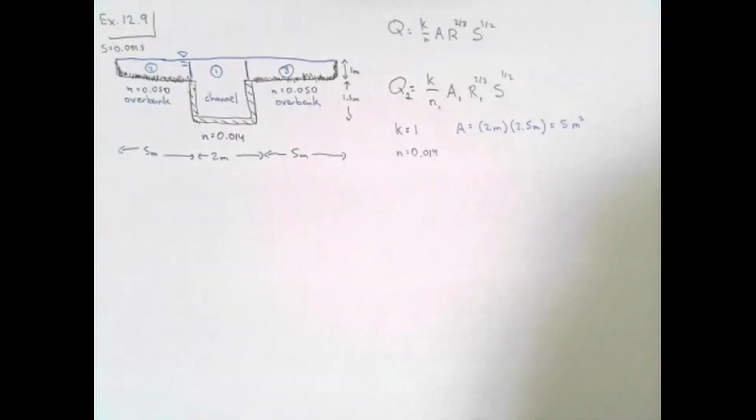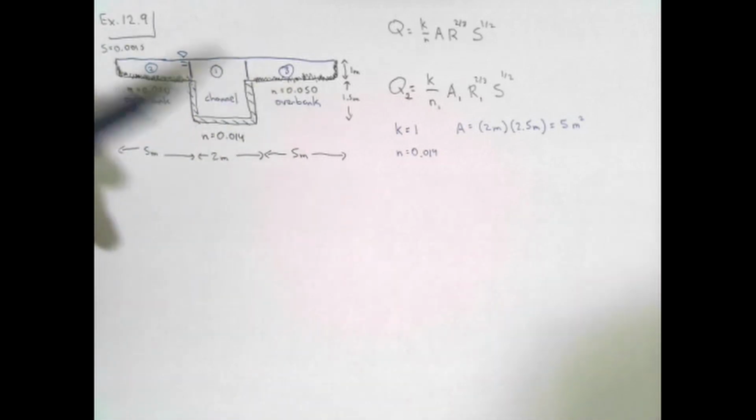Now, there isn't a textbook solution for choosing the method you want to use. You can use this, and you'll find that for some channels, splitting your channel into these vertical segments doesn't give you realistic answers. So I do want you to be aware of that, especially for the take-home exam. Be aware that this methodology won't always work. And if that doesn't work, you're going to have to find different ways of reconciling these different roughness coefficients. But we're going to talk a little bit more about that later.